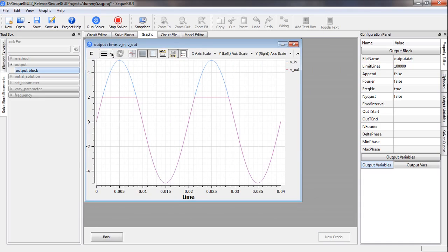Alright, so that is our result. And as we expected, if Vi is greater than 2 volts, that is Vr, our output voltage is constant, that is equal to Vr. Otherwise, Vo and Vi are equal over here.